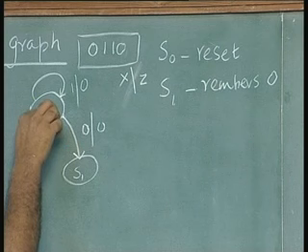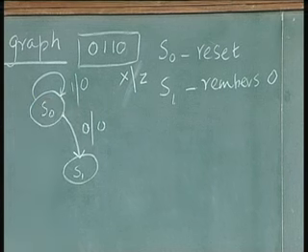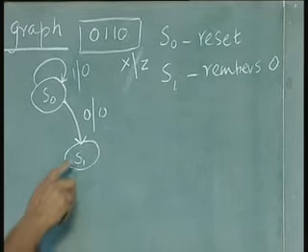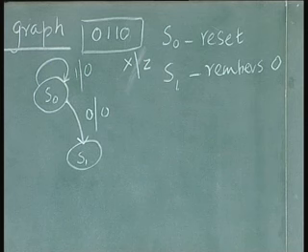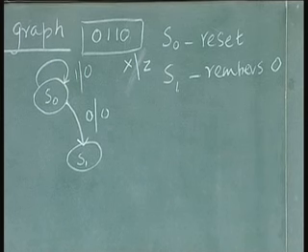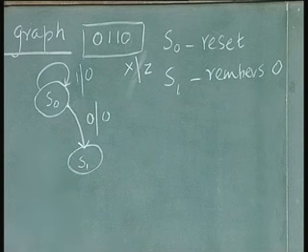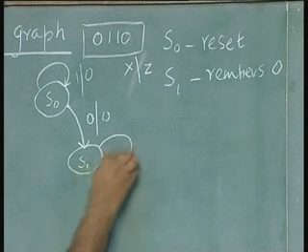So, I have exhausted in S0 what happens if 0 is input and what happens when 1 is the input. Likewise, I have to do this from each state, S1. In S1 state, if a 0 occurs, I do not have to store it again, because S1 is a state where 0 has already been memorized. There is no point in recording the second 0 because my pattern requires only one 0. The latest 0 can be taken as the 0 of the pattern and I discard the previous zeros. So, if 0 occurs, I continue to be in this state.